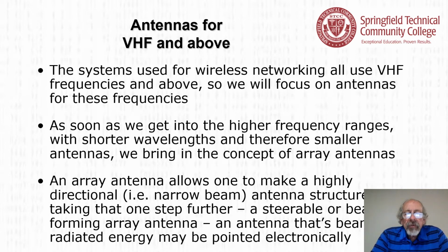Again, we'll talk about antennas for VHF and above, which is 300 megahertz and up. The systems used for wireless networking all use VHF frequencies and above, so we'll focus on antennas for these frequencies. As soon as we get into the higher frequency ranges, with shorter wavelengths and therefore smaller antennas, we bring in the concept of array antennas.